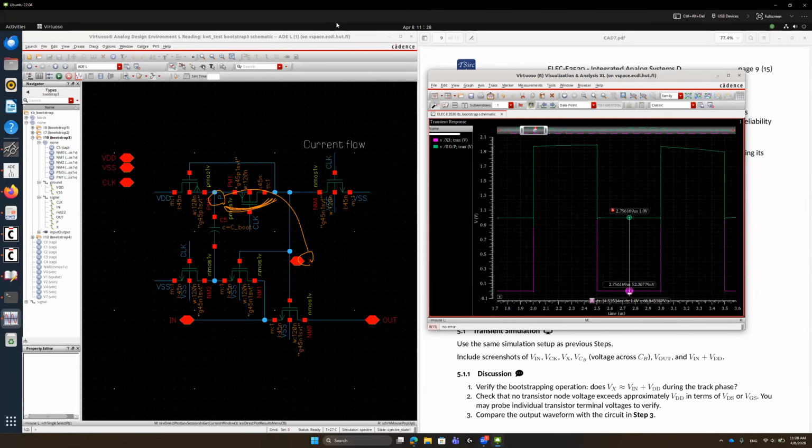This is because in other cases, in the hold phase, this gate voltage goes to 0 volt, which is connected to here. And if this voltage is 0 volt, then this is also 0 volt, the gate voltage of the PMOS. Then the P node will be connected to VDD. Then that's all. VDS is as high as only 1 volt. So in terms of VDS, that's fine.